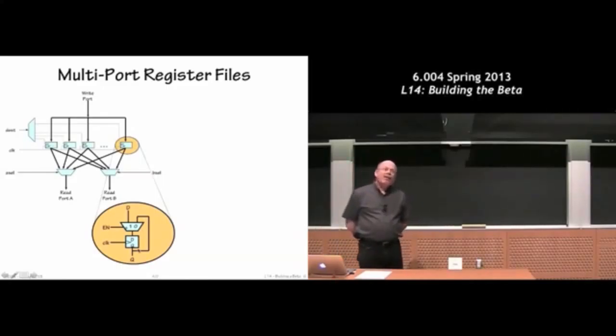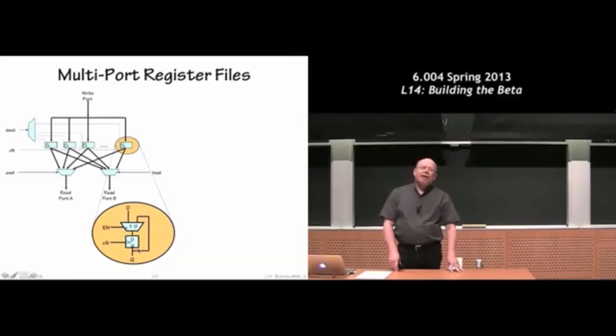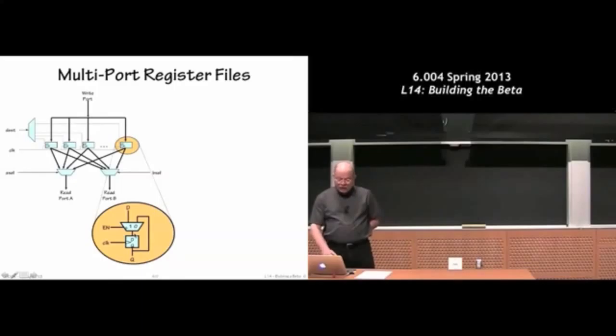So you can say, well, why don't we just do something fancy with a clock, do some logic so that the rising clock edge doesn't happen. And that turns out to be fraught with danger as you get down to low-level circuit design. And it turns out that this little diagram here, which involves this little 1-bit multiplexer, is a much safer way of implementing clock-enabled registers. And so almost all designs that I know of do that.